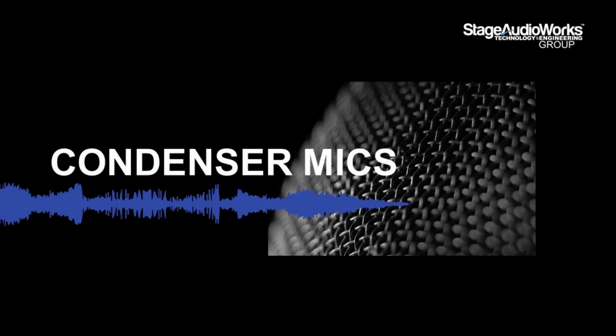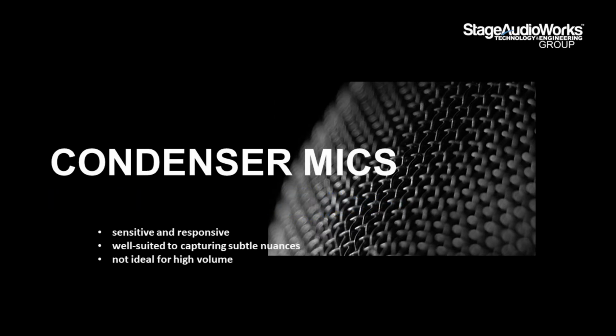Condenser mics, these tend to be more sensitive and responsive than dynamic mics. So they're quite well suited to capturing subtle nuances in sound. Not that ideal for high volume work, as their sensitivity makes them prone to overloading and distortion, those types of things. So condenser means capacitor, which is an electronic component that stores energy in the form of an electrostatic field.